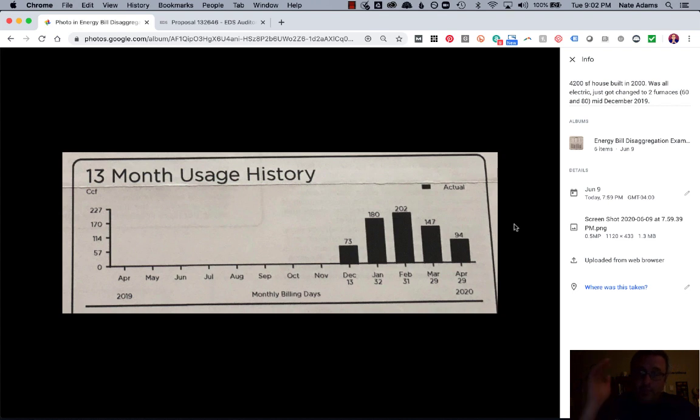So anyway, when I trued this, and I'll record that next, I was truing it to 1,000 therms a year. So I was figuring that they were going to spend $600 or $700 a year for heating, because again, 70 or 80 cents per therm here. And then they were using 4,000 kilowatt hours a year for cooling, somewhere in that ballpark. So I was truing it to something like $450 for cooling cost for the year. And so those really helped me figure this out.